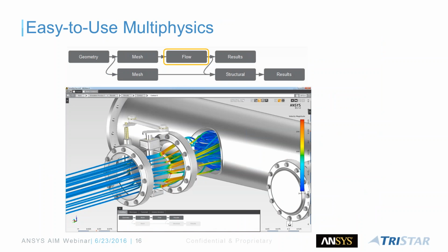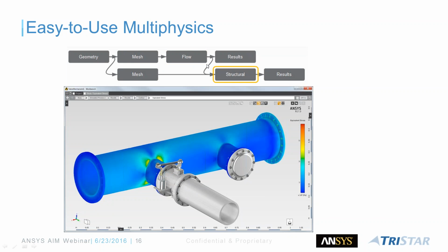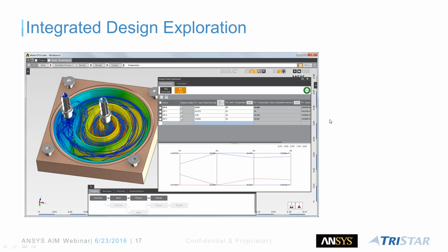And here is the multiphysics one that I was talking about earlier, wherein first you import the geometry, mesh it, and then you would apply the boundary conditions, right? Your inlet, outlet, and you would control the mesh if required, and then you would assign all the required boundary conditions for the fluid flow itself, and it runs through that single physics. At the same time, it knows to provide results or get the required information from the fluid flow analysis to the structural side, and maybe even do design exploration. So what you're seeing there, those grabs that you see, are the design checkpoints, or it could be dimensions from the CAD geometry, or dimensions or parameters that you got from SpaceClaim's editing tool, right? Either way, you can expose dimensions and parameters and say, okay, these are my different design checkpoints, and I would like to see what is the impact on the results when you make those changes, right?